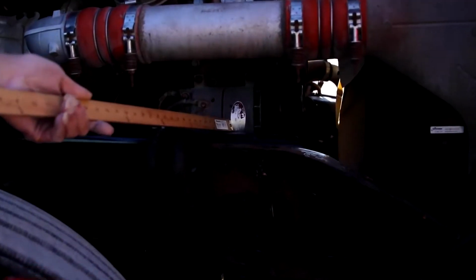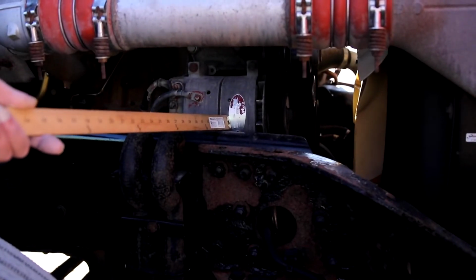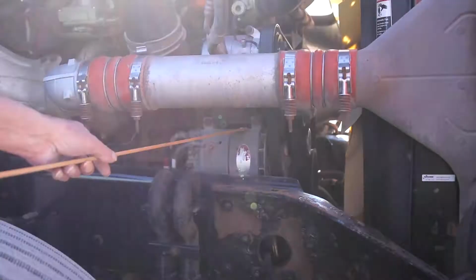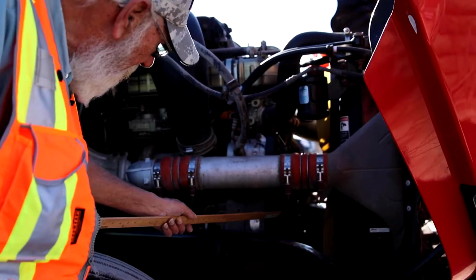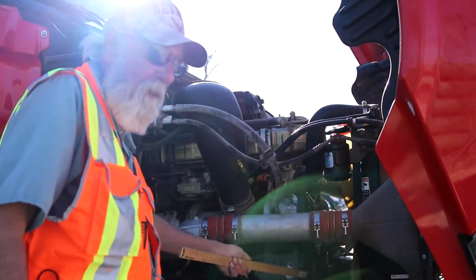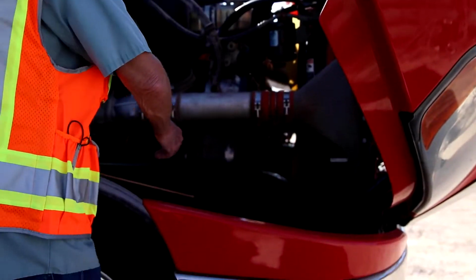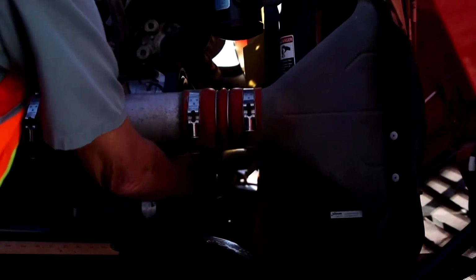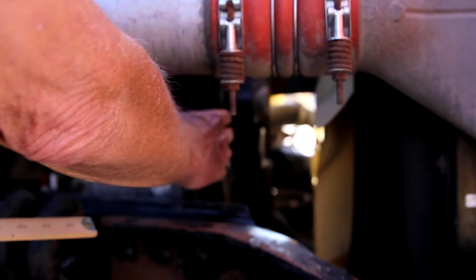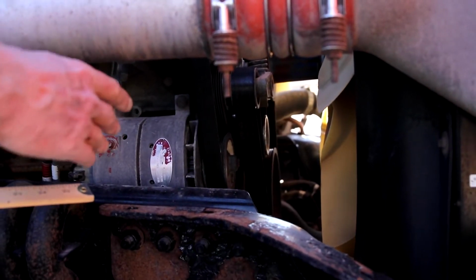Next down, we have our alternator. It is mounted securely to the vehicle. It's not bent, broken, or cracked. Mounted securely to the vehicle by nuts and bolts. It is belt driven, and the belt itself must not have more than 3/4 of an inch of play and no tears or frays on it.